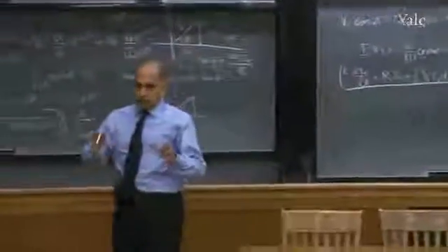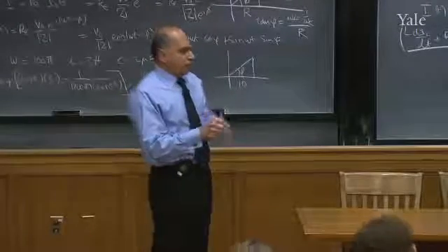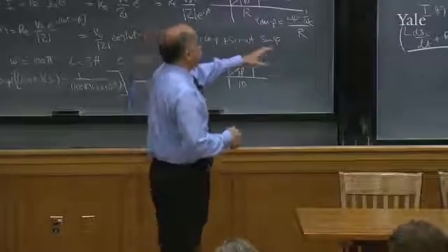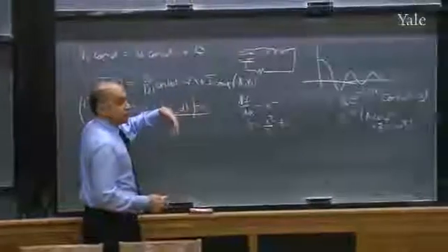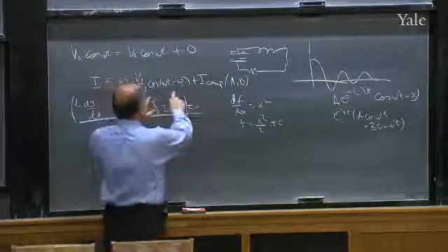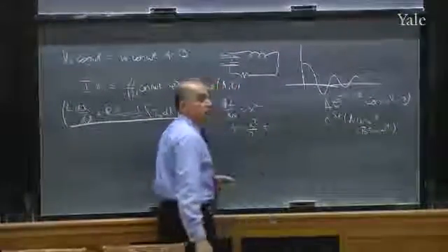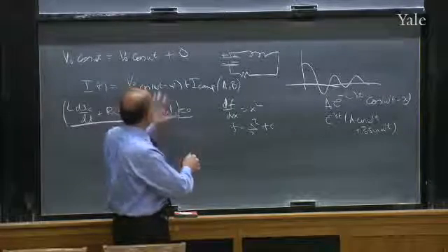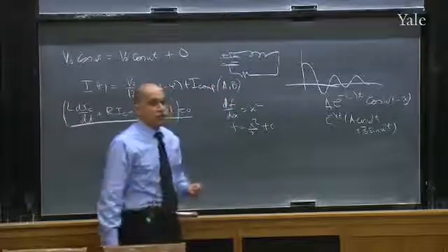In other words, if you took the LCR circuit and took a generator and you hooked it up, from the instant you hooked it up, it won't immediately assume this form that I have here. Because, for example, at t equal to 0, maybe the current is 0 in the real problem. This current doesn't vanish. But you should add to this function, and choose a and b so that the current vanishes at t equal to 0. You can fit the actual experiment to the solution by choosing a and b to match the initial current and, say, the initial charge on the capacitor.